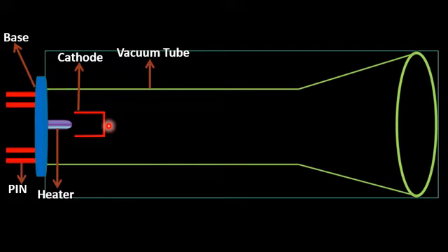So in order to focus the ejected electrons, the cathode is covered with a grid. The grid is a device which moves the ejected electrons forward in a stream in a straight path toward the phosphorescent screen, and furthermore the grid increases the acceleration of the electrons. So the grid has two roles.